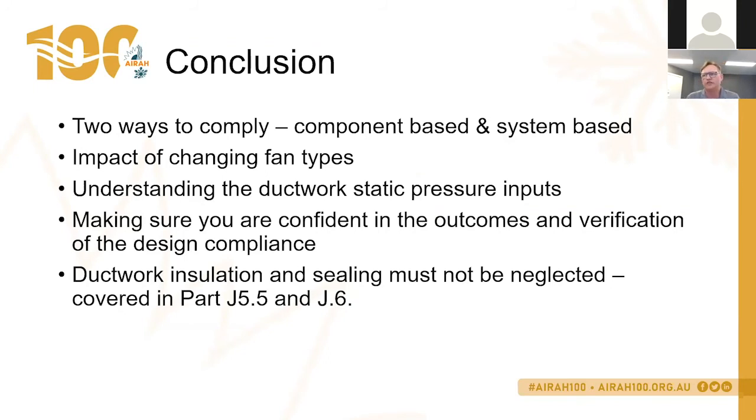So in conclusion, there's two ways to comply for the fan system efficiency and ductwork compliance. You can comply via component-based or system-based approach. There are impacts of changing fan types on your minimum efficiency requirements. Understanding the ductwork static pressure inputs, so making sure you go through the calculator and understand when and where you need to input certain requirements. It's quite critical, and they are slightly different to what you would use from a contractor or specification level.